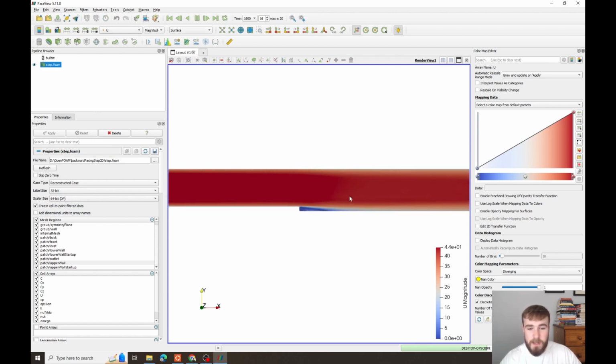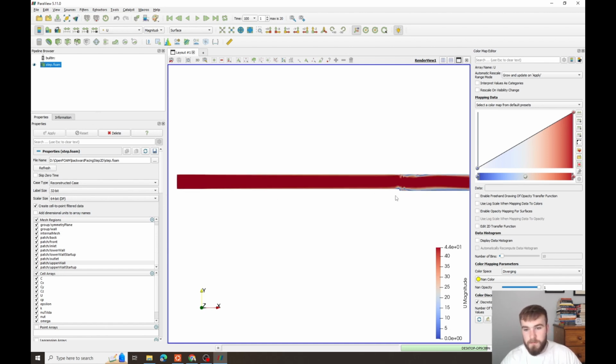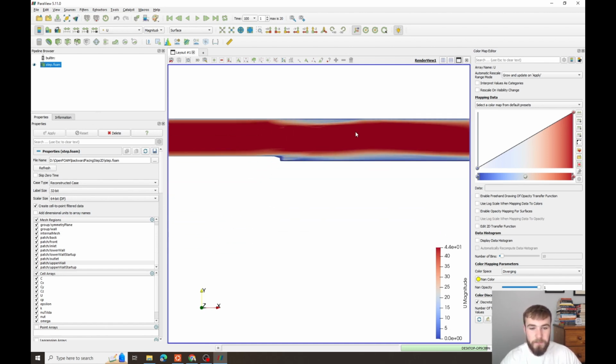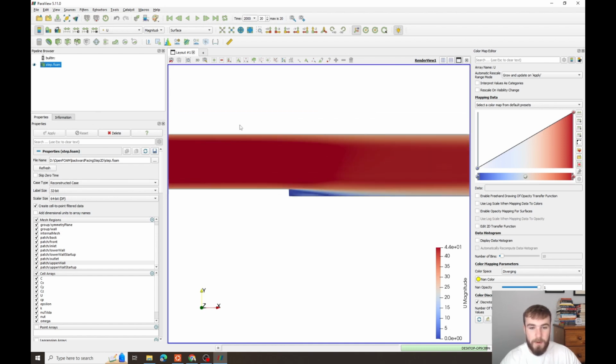And you can see that as the simulation progressed, our flow field started to develop. So velocity was pretty much 0. Then our velocity basically developed from the inlet. And we got our simulation to converge to what we would expect. Okay, so you can see as I move on, the simulation is not really changing that much more, and that's our backwards facing step.